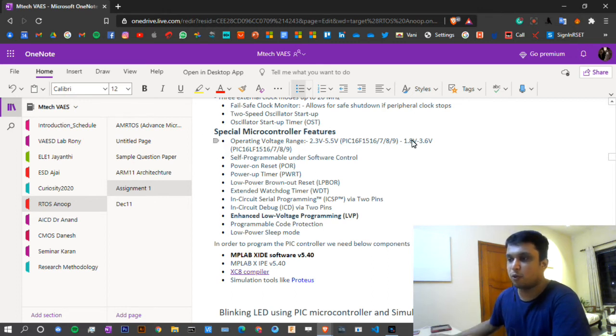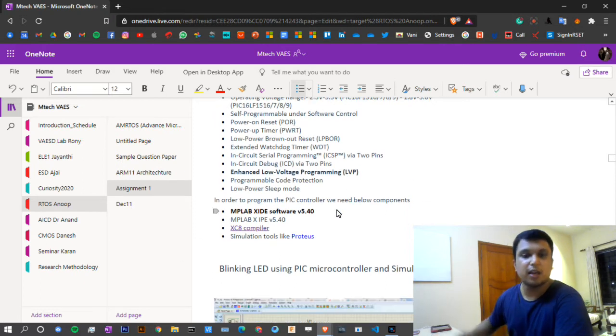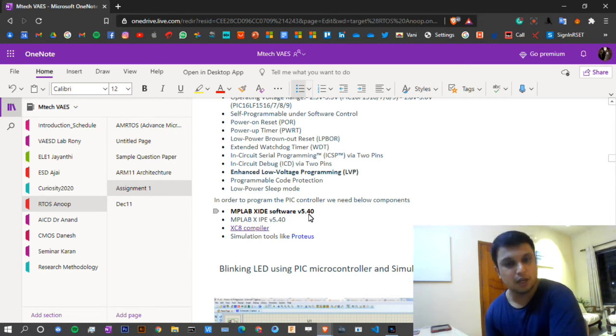Here for this assignment, we will be using MPLAB Xpress software to write code in C language, which will be converted into assembly language, and then to machine code in HEX. It's converted to HEX code, and this HEX code will simulate the circuitry in Proteus, and we'll run this C code inside the PIC microcontroller in Proteus to see how the program executes.